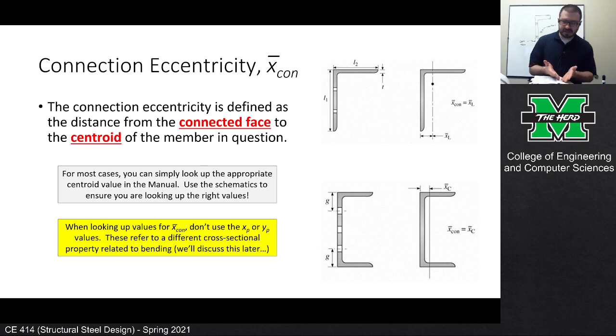If you look at the C shapes, on the left page are all the dimensions, and the right page are all the properties. I want to look at axis YY on the page on the right. You should see 6 properties listed. There's an I, that's the moment of inertia. S is the section modulus.